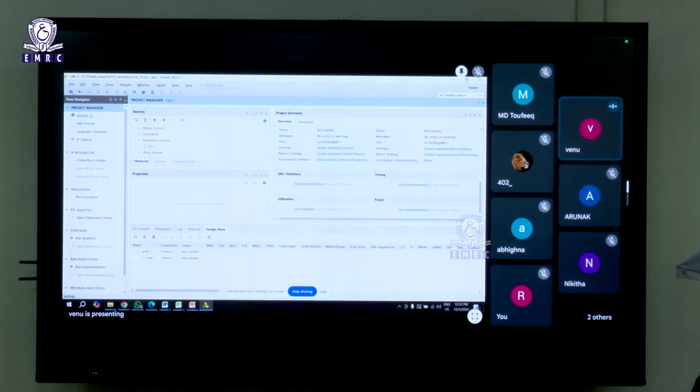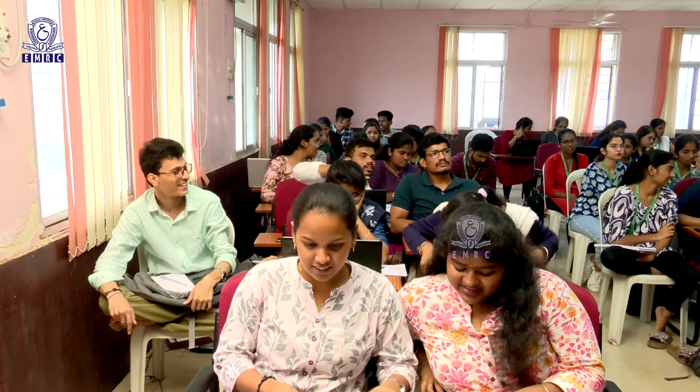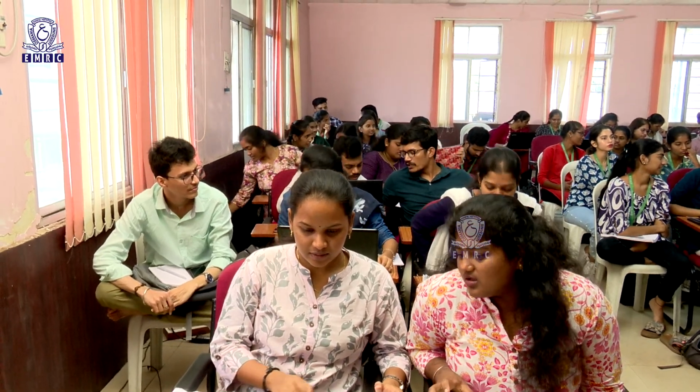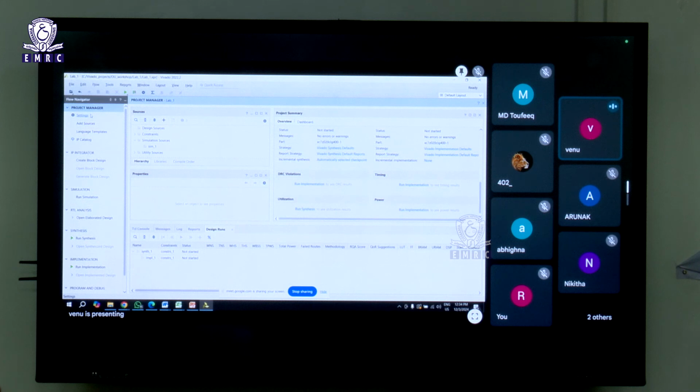When we say we are coding the LUTs or putting the logic onto the LUTs, we are saving that data onto the LUT. Whenever there is a function that calls for the logic of AND, what the FPGA does is look at this stored data, which is the truth table. It will see what the inputs are and compare them with the data already stored on the LUT, and it will directly say, okay, 1 and 1, this is 1. It is directly taking the reference stored on the LUT and giving you an output. The simpler example is the AND gate. It can be as complex as we want. We will understand with an example how this is getting translated and why.